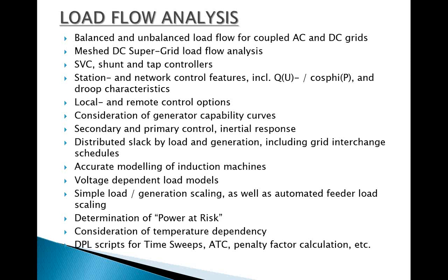Determination of value at risk can be done. Consideration of temperature dependency. DPL scripting for time shifts, ATC and penalty factor calculation can be done. DPL generally stands for DIgSILENT programming language, where we can write our program and give automated scripting through the network, and also provide dynamic inputs to the appliances which we are using in our PowerFactory network. So these are some basic features and the parts of analysis we can conduct in load flow analysis.